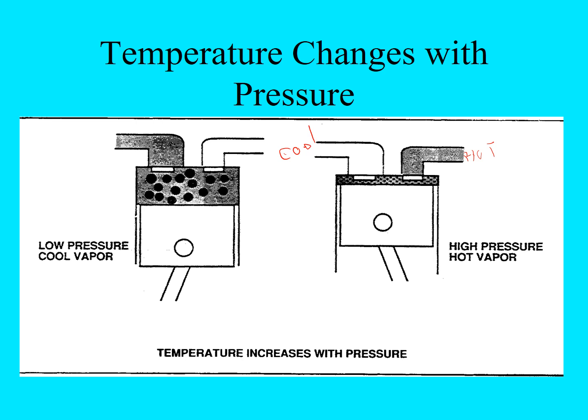If it does compress, something's got to give. We've found bent connecting rods in a vehicle because of liquid coolant getting into the combustion chamber and the engine trying to compress it. So let's take a look at the refrigeration circuit.